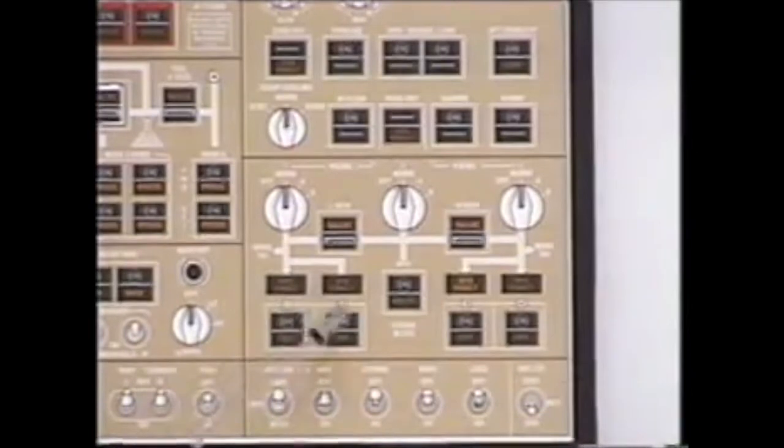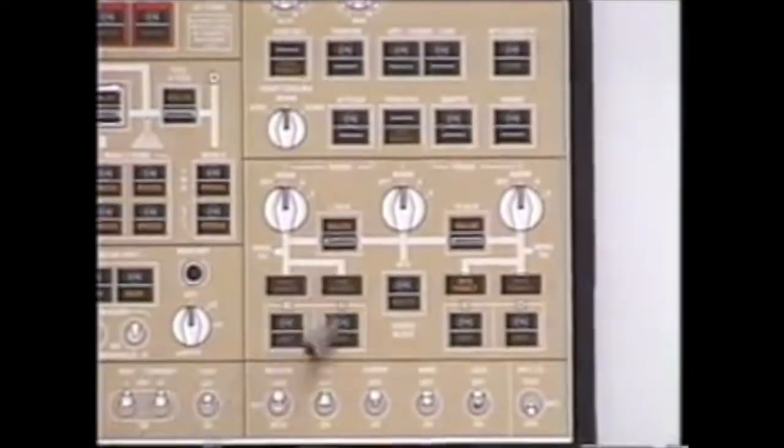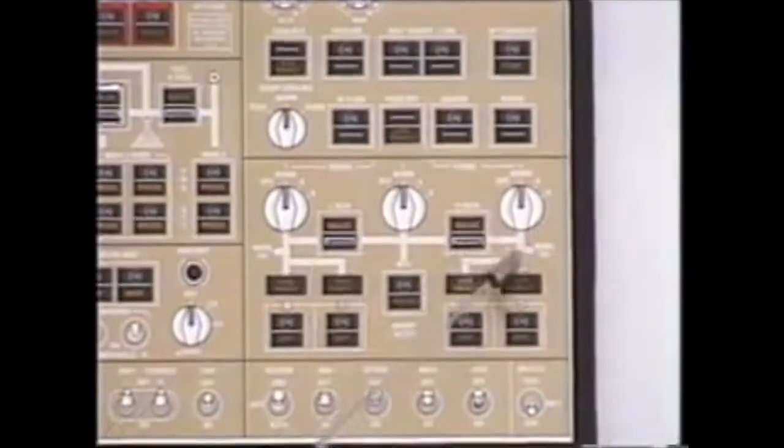On the wing manifolds, between your engine bleed valves and your isolation valves, the left wing manifold and the right wing manifold, there are several items: the air conditioning pack, the air demand pumps, wing anti-ice, and leading edge flaps. Also note that the hydraulic reservoir head pressure receives pneumatic air from the respective wing manifold.